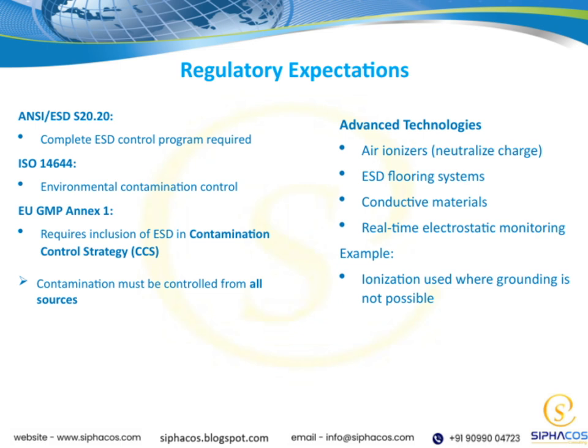Another key technology is real-time electrostatic monitoring. This allows us to continuously track static levels and ensure our control measures are working effectively. For example, ionization is often used where grounding can't be implemented easily, providing an alternative way to neutralize static charges.